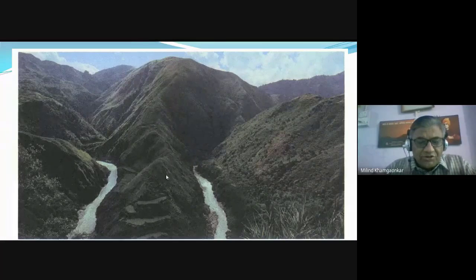This is the ridge. As I have told you just now, this ridge divides the catchment area of this stream as well as this stream. That is, the catchment area is nothing but all this area between this ridge and this ridge for this stream, over which when the rainfall occurs, the water reaches this stream. The same holds for this stream, with this ridge and all these ridges. In between, all the area over which the rainfall occurs, it reaches the stream.